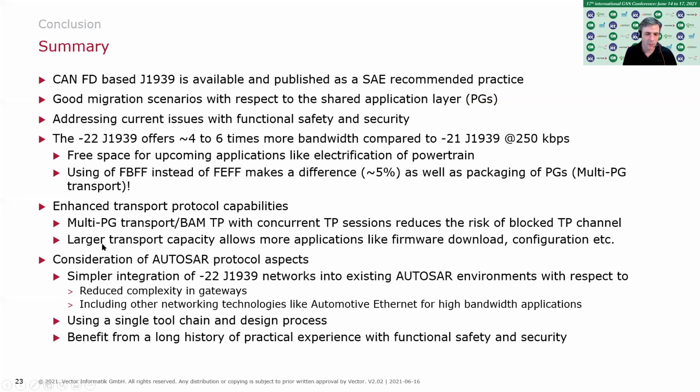this is considered very helpful. And then the AUTOSAR protocol aspects, for some companies, this is really a very, very helpful overall design aspect, because that will help to reduce the need of protocol translation. And you can use the same tool chain and design process. It's not like you do everything in AUTOSAR and then J1939 separately, so everything is now the same.